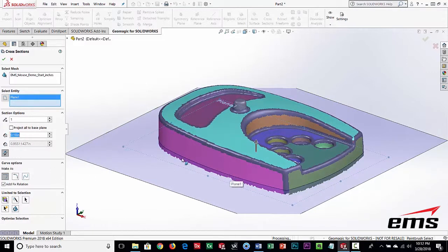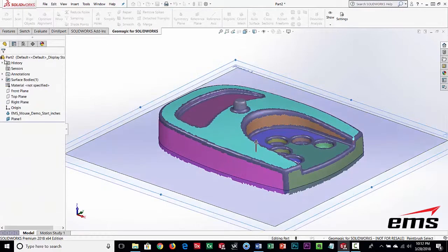What you see here is this dark line, and basically that is cutting a section through the scan data, okay? But again, we can't cut it. We want to build that sketch on that bottom plane, but there's nothing there. So I've moved it up, and typically we don't want to be right on the corner anyway. Scanners cannot scan a sharp corner, so you're always going to have rounding. So we're typically moving up a little bit and sampling, and I'll say, hey, that looks fine.